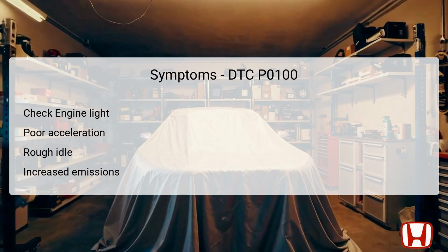Symptoms associated with DTC P0100 include the illumination of the check engine light, which serves as the vehicle's alert system for malfunctions. Drivers may also experience poor acceleration as the engine management system struggles to adapt to inaccurate airflow data. Furthermore, rough idling can occur due to irregular fuel mixtures that affect engine operation.